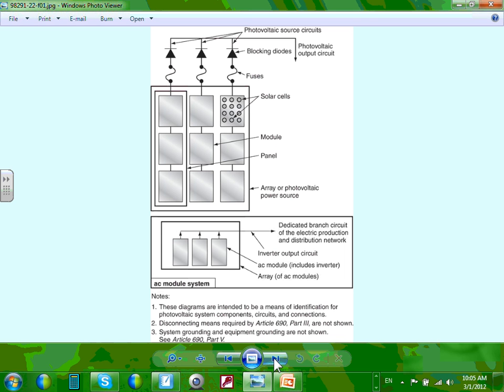Voltages, the limitation, guys, is 600 volt for most of the systems that we do, just because of conductors, but you can go higher than that, unless you're in a dwelling. For a dwelling, your limitation is up to 600 volt. For other commercial, we're doing commercial, you can go higher than that. But if you go higher than 600, you get into a whole regulation for over 600. So most of the systems are limited to 600 volt or less. Any question, guys, about that? Okay, that's about it. Thank you.